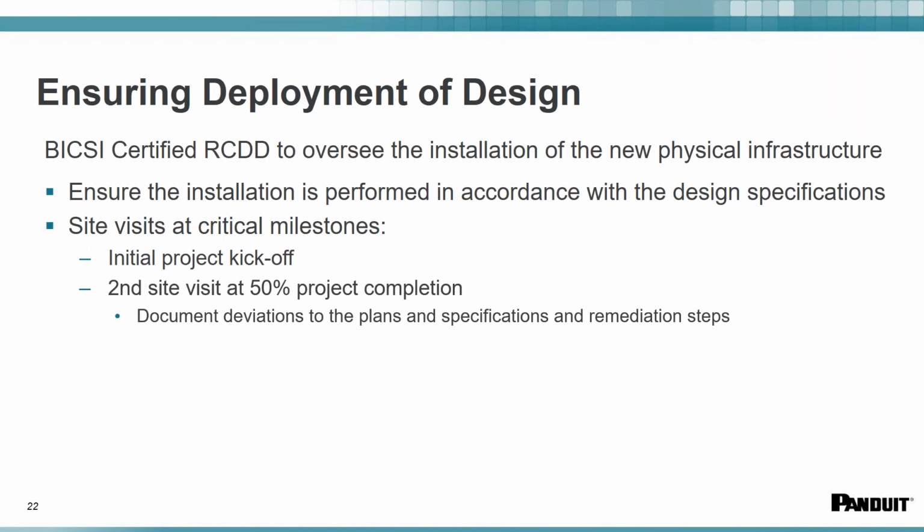When you're running the copper, you have to make sure, are my communication losses still acceptable? When you start connecting the control system, that's where you come in and start testing your program. But before that, you are doing all of these different visit steps to make sure that the architecture that you designed is continuing to be implemented correctly.